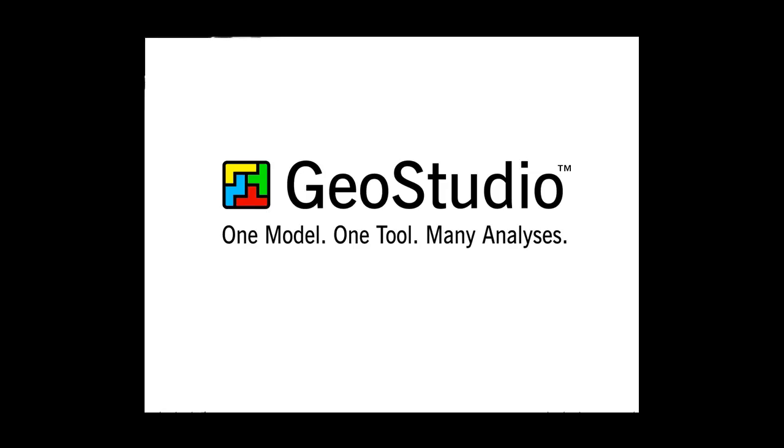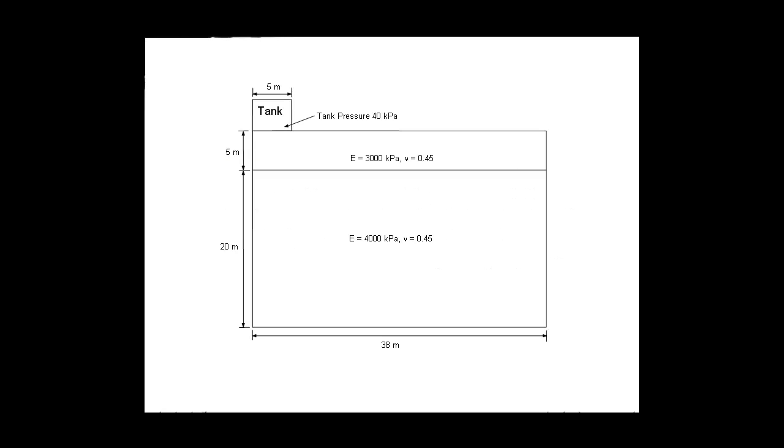The objective of this analysis is to estimate the settlement of a circular water-filled tank. The tank is 10 meters in diameter and 4 meters high. It has a completely flexible base, and the applied pressure on the ground when the tank is full is 40 kPa. Since the problem is symmetrical about the vertical center line of the tank, the problem definition will only include half of the tank, and an axisymmetric analysis will be conducted.